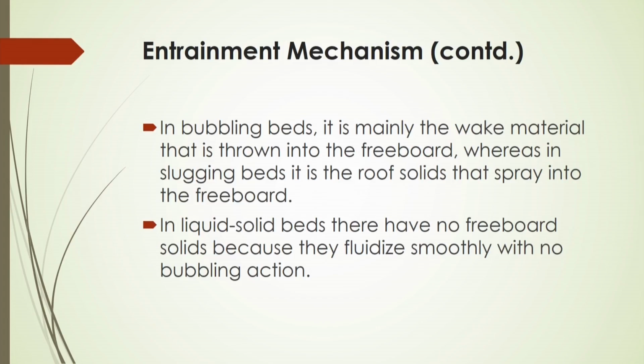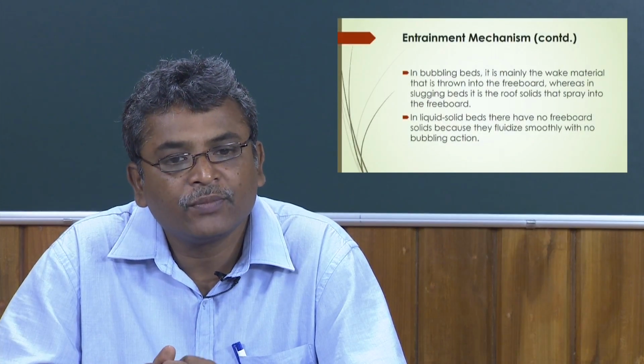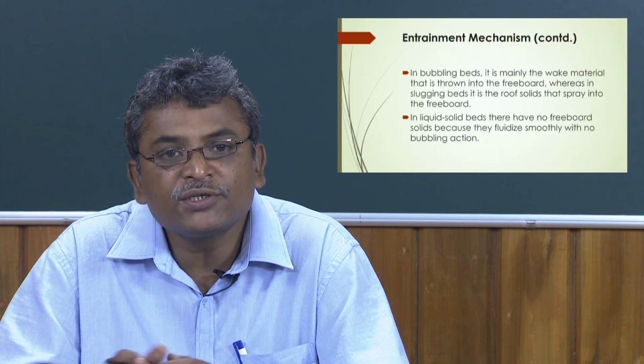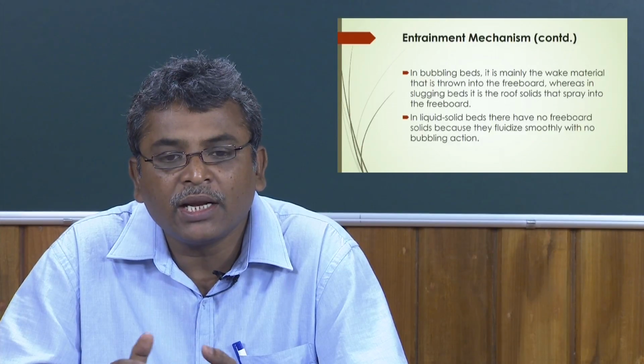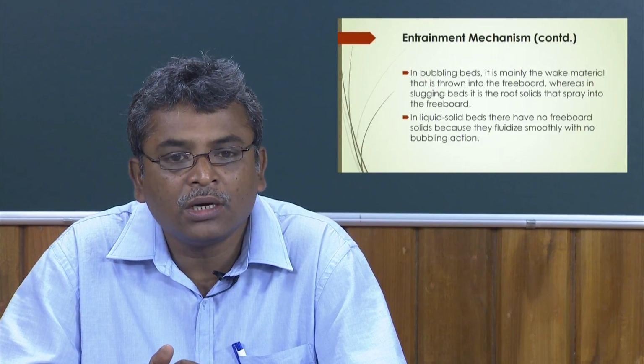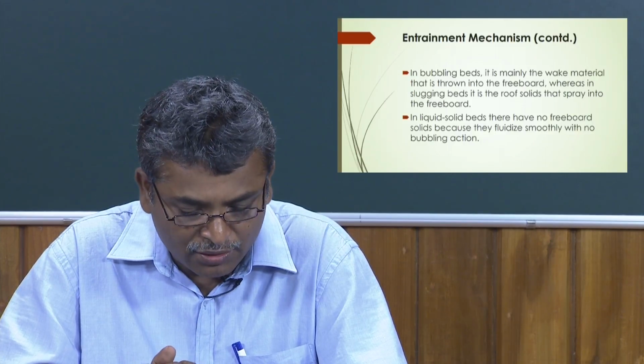In bubbling beds, it is mainly the wake material that is thrown into the freeboard, whereas in slugging beds it is the roof solids that spray into the freeboard. In liquid-solid beds, there is no freeboard of solids because they fluidize smoothly with no bubble formation or action.